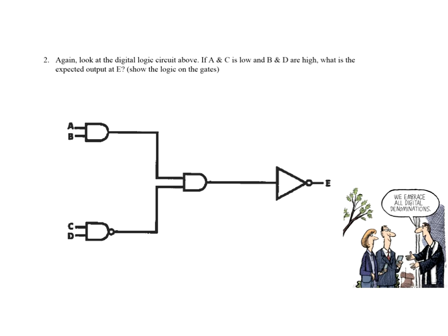Okay, look at the digital logic again. If A and C are low, again, I have a low in A, and this is an AND gate, so what does the output have to be? It has to be low. A low into this AND gate makes this have to be a low. I didn't even have to evaluate this down here. A low coming out, this would have to be a high after it goes to the NOT. All right, so you see we're showing you ways to cut through detailed analysis by having an idea of how these gates function.